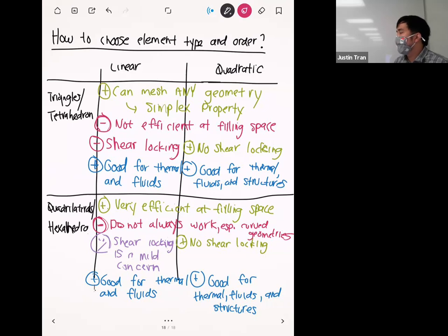And I think a lot of y'all experienced this with the last two activities. And so with the bike crank, it was relatively blocky, but it still had some curves to it. And so I saw that there were quite a few computers that really struggled to make the hex mesh on it. And then with the last activity too, with the cylindrical post, I noticed that some struggled to do that as well. Okay. And so if you can't put a hex mesh on something, it's not the end of the world. So don't stress about it too much. But it is better if you can.